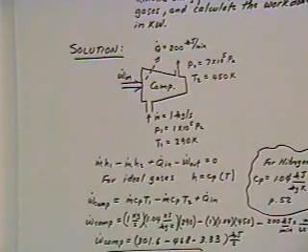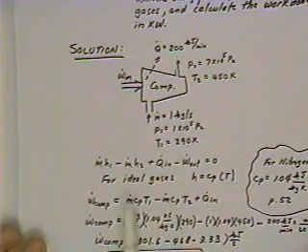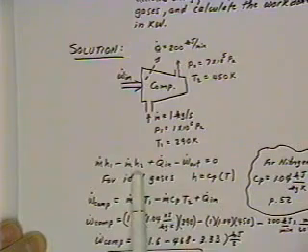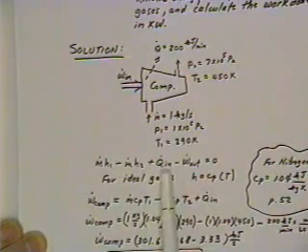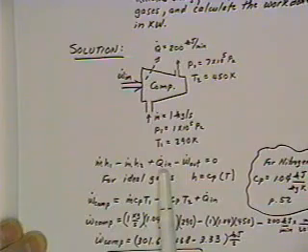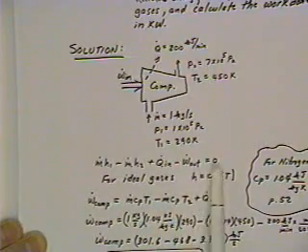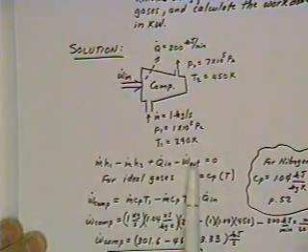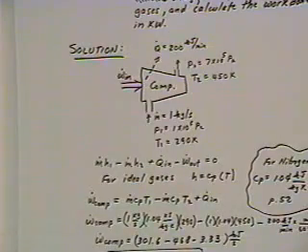All right, so if we go down to our first law as a rate equation, we are neglecting the kinetic energy term, we're neglecting the potential energy term, so that leaves us with mass times enthalpy entering minus mass times enthalpy leaving, plus heat transfer into the system. In this particular case, we've got Q out of the system, so we know when we plug this in it's going to be negative, minus the work out for the system. And in this particular case, we know that we've got a work input, so we know that the work out term is also going to be negative.